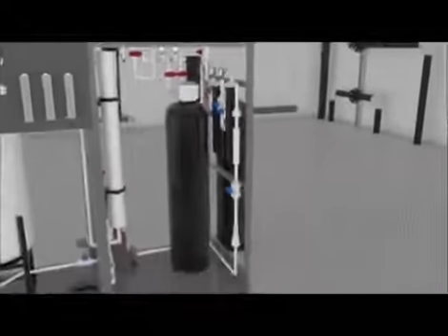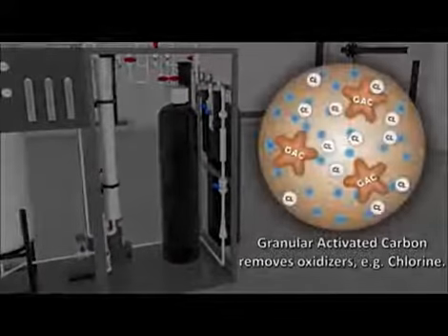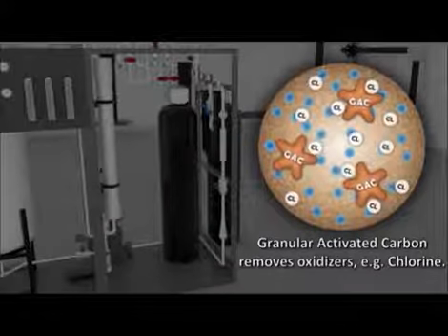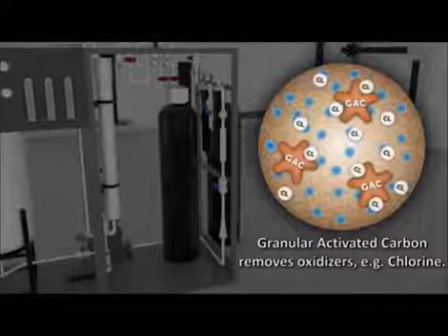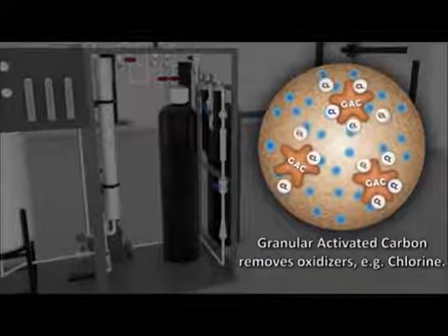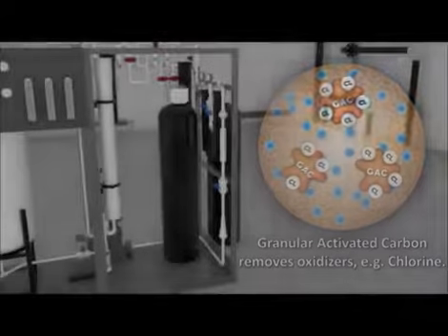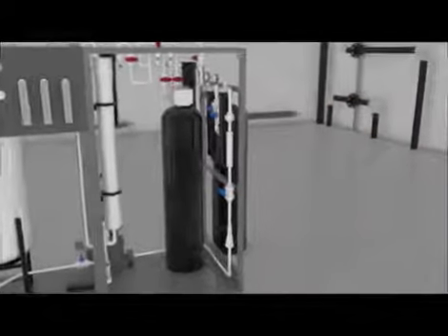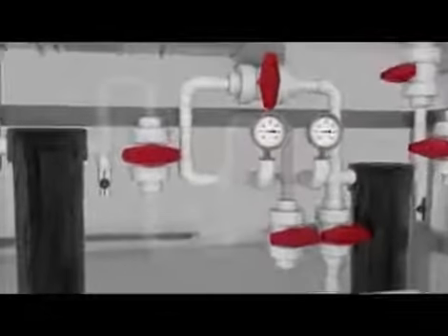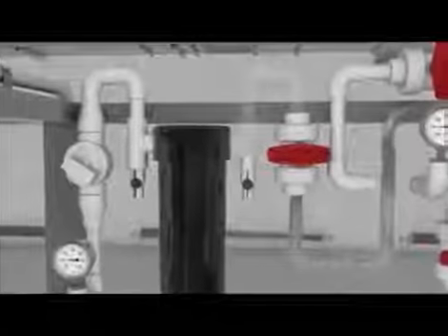Reverse osmosis is sensitive to oxidizers such as chlorine, typically found in all city water sources. Therefore, the Process and Water RO water system includes granular activated carbon, commonly called GAC. The GAC is an absorbent and will reduce the levels of chlorine being sent to the RO membranes. The effluent of the carbon column passes through a higher micron capture filter to capture any carbon fines that may have been released from the vessel.